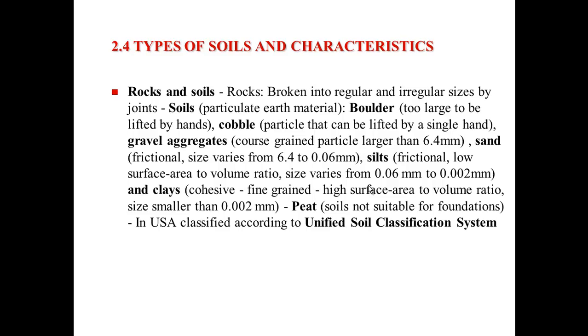So it's just that variation between temperatures and water control that makes silts and clay a difficult material to put building structures on. We do it in this area because we have so much of this material, but it's important to also include good drainage material as backfill into our foundations to make sure that they work well.